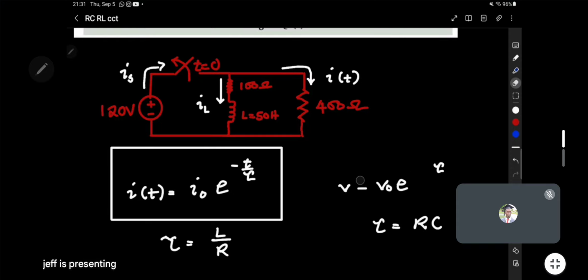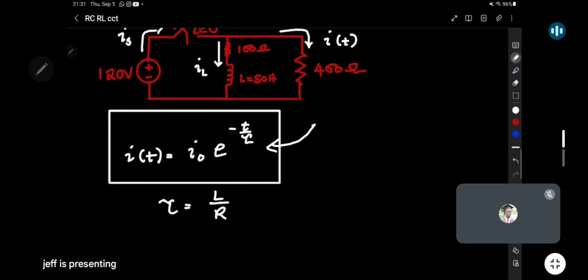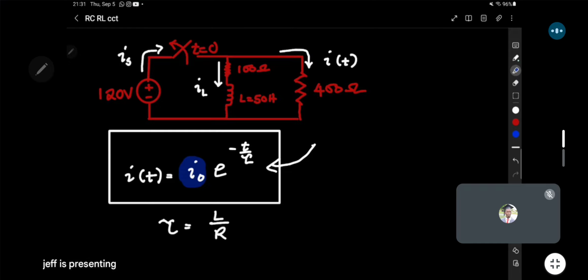Again, here, we're just focusing on our inductor. So we see that to get the expression for the current I coming from the inductor, we need two things. Firstly, we need to know what the initial current was, the initial current in the inductor. What was it? It's the current that was passing in the line with the inductor at t less than 0.